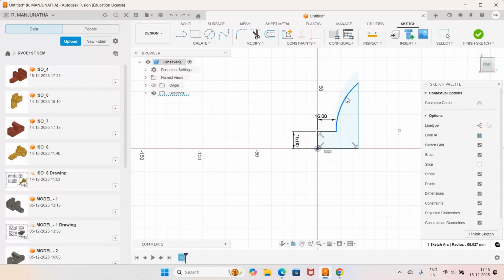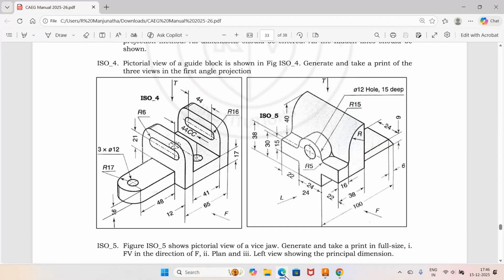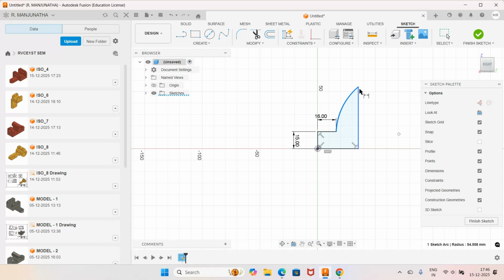Okay. Now I want this height. So what is the height of this? The height is 40 mm. So from 15 you have 40. So you will go for dimension from here to here. Take 40 mm height. Okay. Then you have 15, so automatically this becomes the constraint. Then the total distance is a dimension. You take this as 38. So automatically this has been constrained.